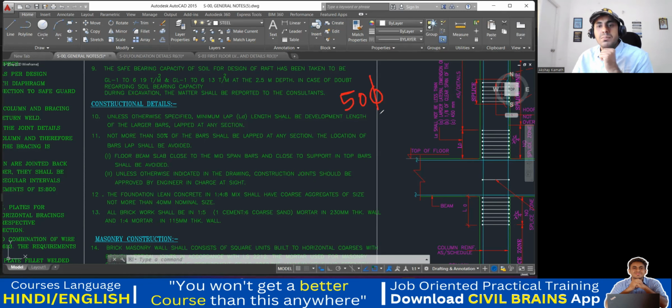Usually we can take that. But if it is mentioned in the drawing, then we have to take that. So it's telling us you can take 50 times the diameter of the bar. Then it's adding one more word, of the larger bar. Suppose you have two bars, this is bar number 1 and this is bar number 2. This is a 16 diameter bar and this is a 12 diameter bar. So out of 16 and 12, which is larger? 16. Then I'll take care of 16 here. So 50 times 16 is 800 mm. So 800 mm will be my lap length. Got it?